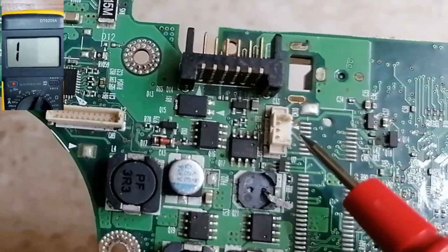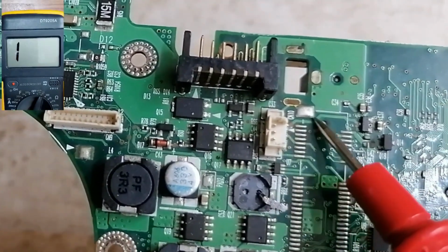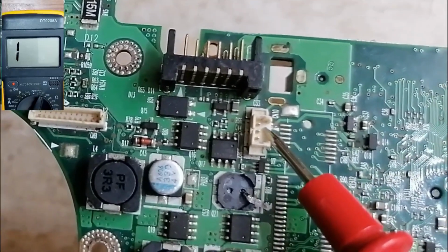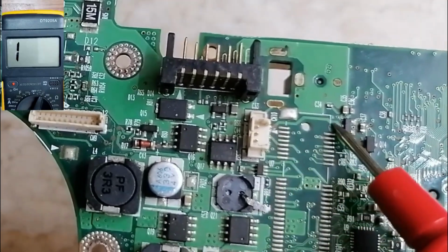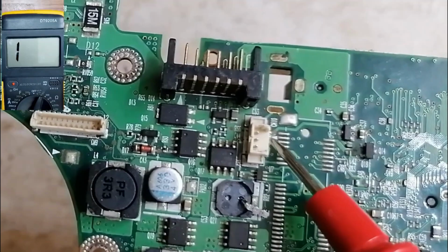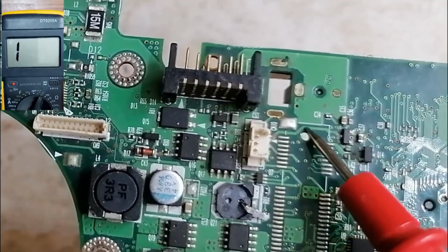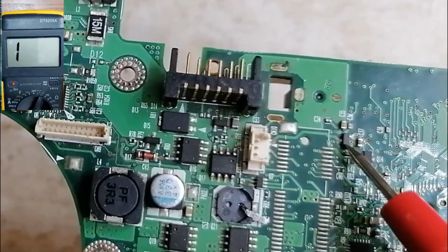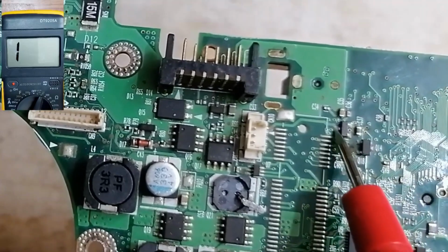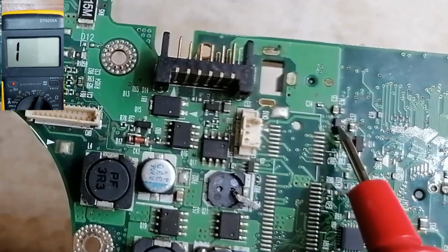So we have a very clear example here. Do you see this connector? Here we have this bold line, which means this is the connector for the fan that cools down the CPU. This bold line means the connector receives 3.3 volts here. But if you find that 3.3 volts is missing here, you can just follow this path like this, as you can see. We have this transistor here. This transistor is the component that generates this 3.3 volts. So if 3.3 volts is missing, you should check this transistor.